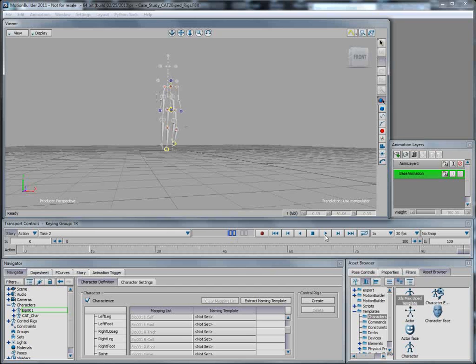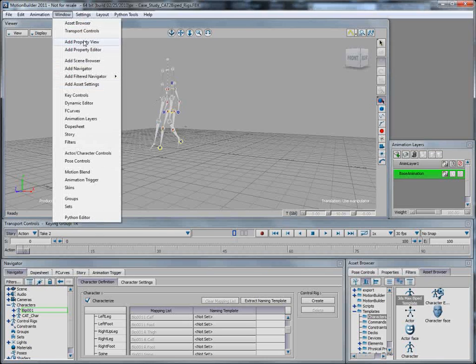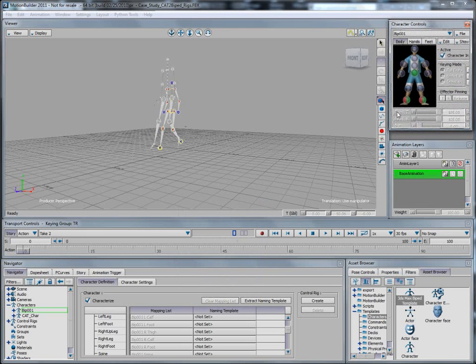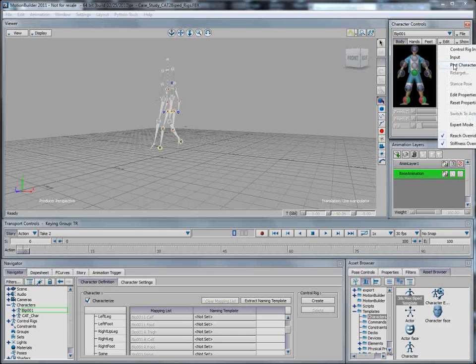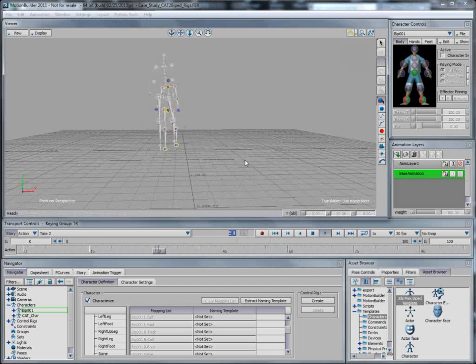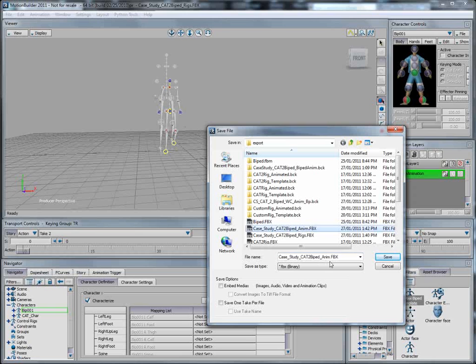To be able to re-export that to 3ds Max, what I need to do is to go back to the character. Where did I put this one? There you go. So I'm going to put it back on the side here so it's in the front. So I'm going to grab the biped and say File, Plot Character. I'm going to plot that to the skeleton, and OK. And as soon as it's done, we've got our animation on the bones. So we are ready to grab the biped and say File, Save Character Animation, and we're going to call that anim for biped, so BIP.